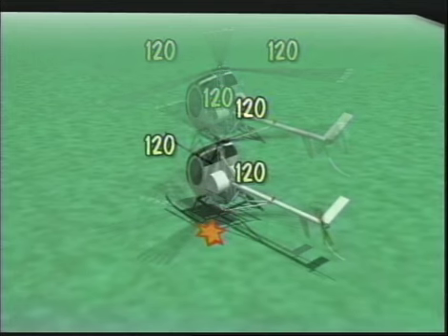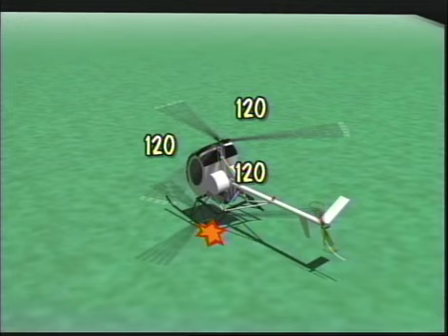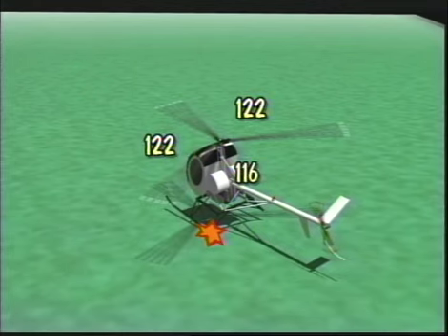When one landing gear of the helicopter strikes the ground first, a shock is transmitted through the fuselage up to the rotor system. This shock may cause the blades straddling the contact point to move closer together, or what is called moving out of phase about the drag hinges. So for example, the spacing might then be 122, 122, and 116 degrees.